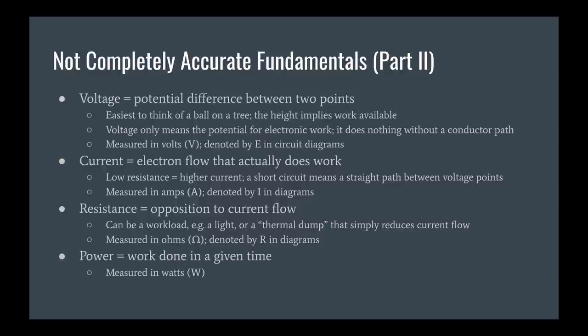So that could be a workload, such as a lamp, a motor, charging a battery or something like that, or a traditional resistor, which is basically just a carbon tube that inhibits the flow of current and basically just dumps that current flow as heat. So resistors get hot. If you ever look inside power supplies, you'll see fairly large resistors in there, typically ceramic, because they can get incredibly hot. I've actually seen ceramic resistors crack because of the amount of current that was going through them.